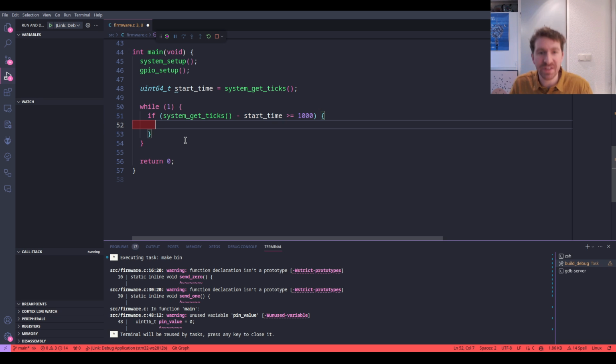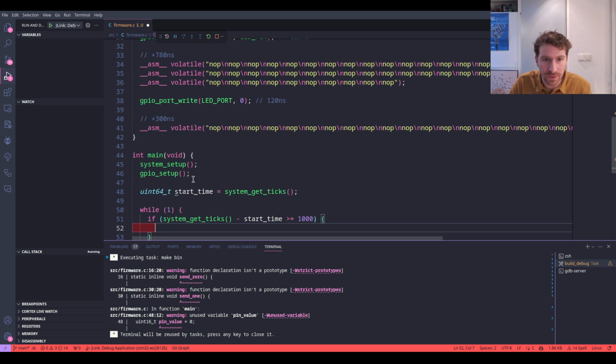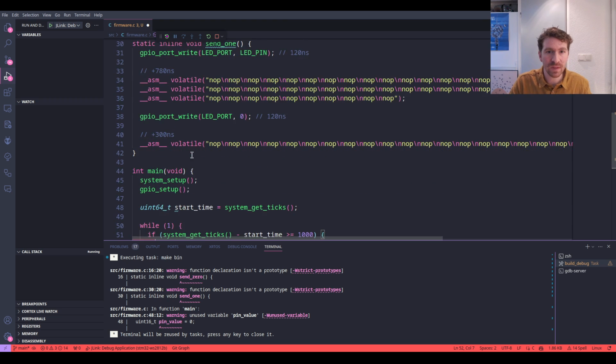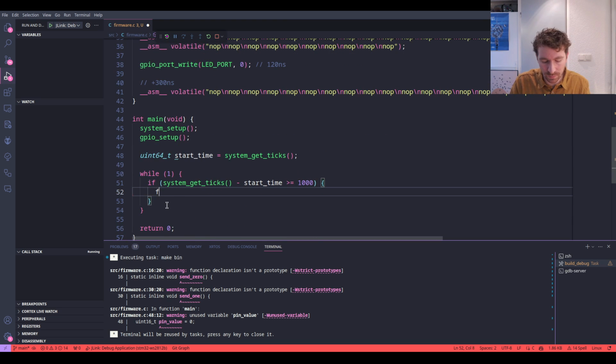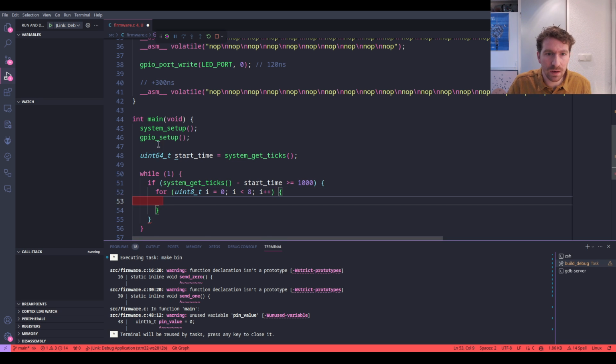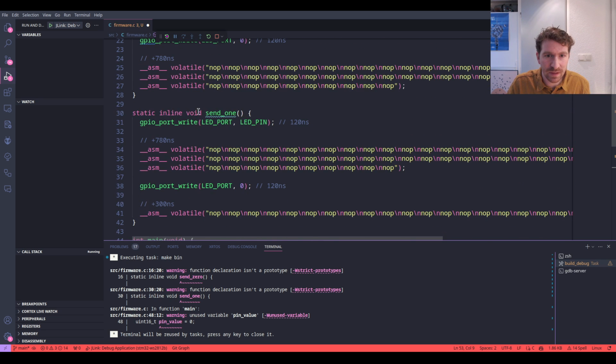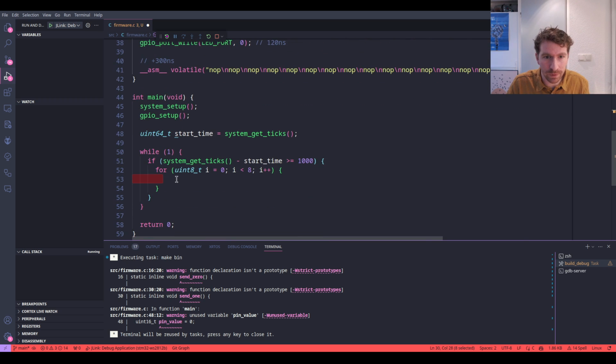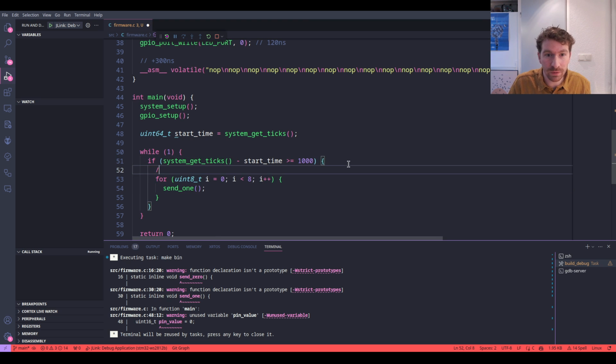If it's been 1 second, then we're going to for i is less than 8 for 8 bits, i plus plus, we're going to send 8 ones in a row here. That's going to be sending the green channel.